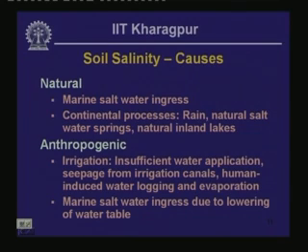Irrigation is one of the contributors to soil salinity, because particularly in areas where subsistence farming takes place involving use of insufficient quantity of water, or because of seepage from irrigation canals, the salt particles contained within the water that is applied get accumulated within the soil voids, and this increases soil salinity, so much so that a large proportion of surface irrigated area in many countries has gone unproductive from the agricultural point of view because of increased salinity.